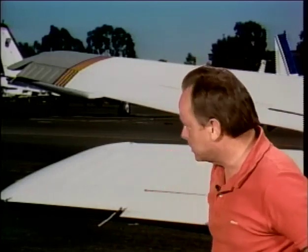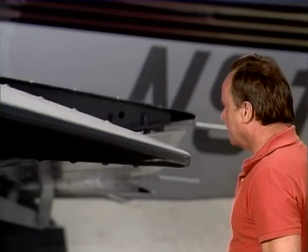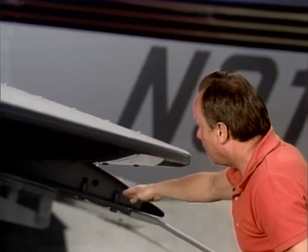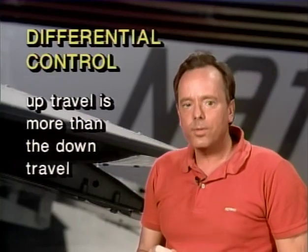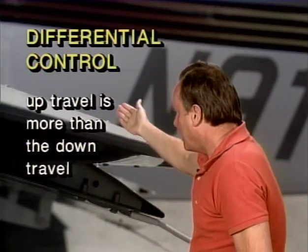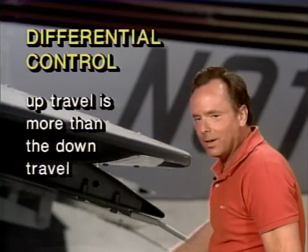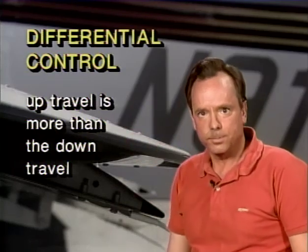All right, now sometimes you have differential controls on ailerons. Let's you and I take a look at differential controls on ailerons. Here's the up travel. It's a great deal of travel and less travel on the down part of the aileron. That's what they call differential control on an aileron system, and it means the up travel is more than the down travel. And what that does is that adverse yaw is eliminated or reduced by having it done that way. Not eliminated, but it is reduced.